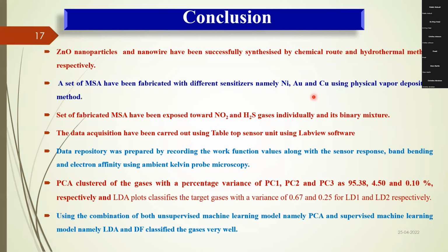The set of fabricated multiple sensor arrays has been exposed to NO2 and H2S gases individually and to their binary mixture. The data acquisition was carried out using a tabletop sensor unit with LabVIEW software. The data repository was prepared by recording the work function value along with the sensor response, band bending, and electron affinity using ambient Kelvin probe microscopy.